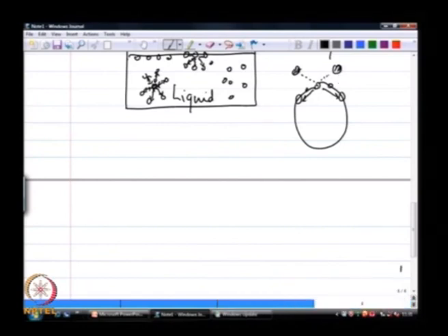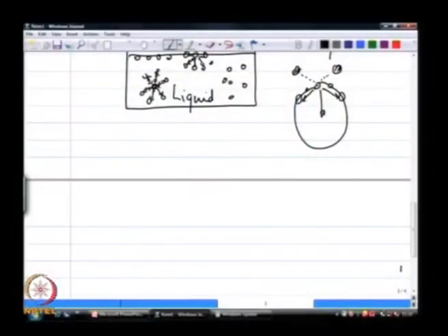The vector sum of all these forces essentially is a force that acts towards the radius of curvature. So, this is again, like I said, do not take this very far in your own mind, it is just to show the concept that there is a stretching force at the interface that causes every fluid entity on the surface to exert a force towards its own radius of curvature. As a consequence, you can see how the whole blob of liquid stays together.